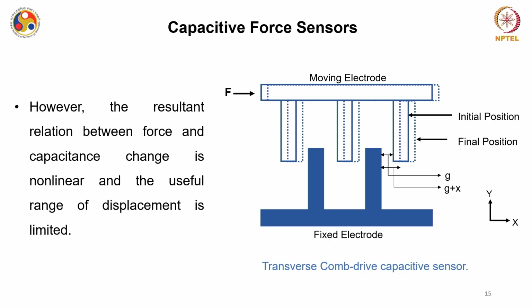Now, I am talking about the non-linearity of this sensor, but please note that even if the sensor is non-linear, as we have discussed in module 1, we can have a linear region of the sensor, where of course you already know the piecewise linear approximation. So from the transfer function you can find the linear region of operation.